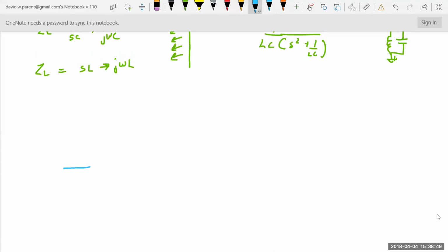So far, we've had a platform with the mass, and that wasn't very interesting. That was just this. And so the velocities are equal, and you can see that in the nodal analysis. The voltage is the same everywhere here. So this input voltage or velocity is the same as the output velocity or voltage.